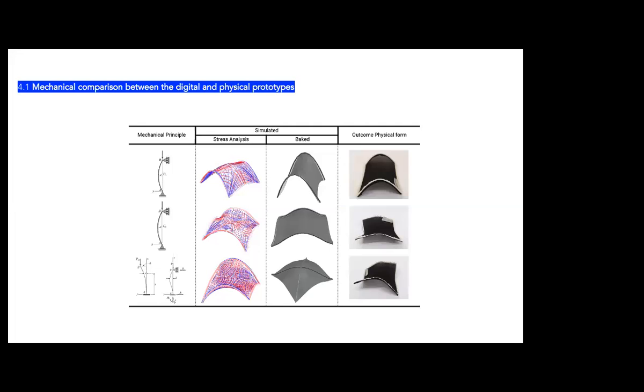The printed pattern works as a continuous and closed geometry under the mechanical principle of deflected buckled columns, transmitting forces between them until they achieve a static equilibrium. Depending on the height and/or the segment of the trace, the energy will distribute until it finds its own stiffness balance. As shown in the image, the deflection principle finds its own equilibrium by distributing forces all across the fabric, generating a deformation and a resultant geometry. With the accurate printing over the textiles, the outcome physical prototype will be structurally adapted, keeping a force balance similar to the simulator form.